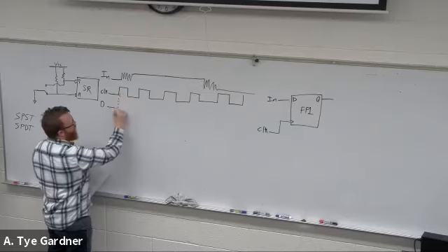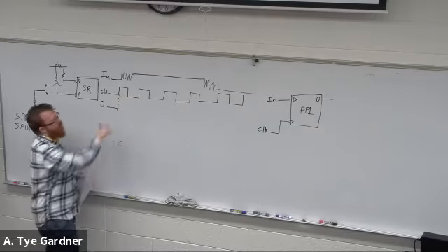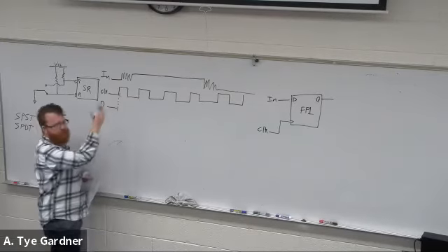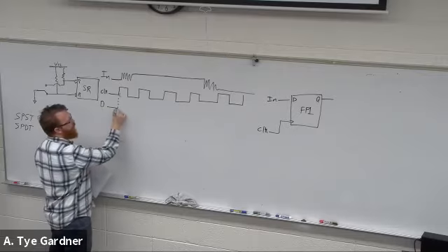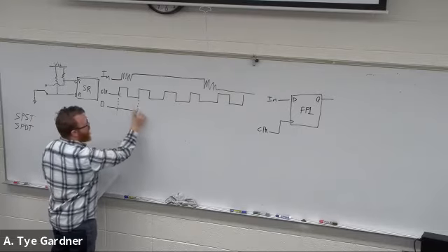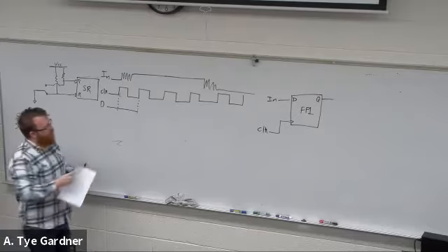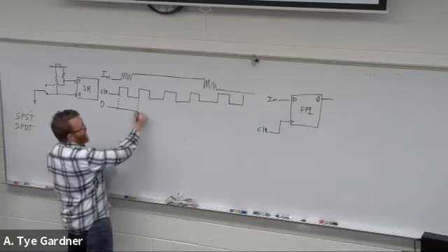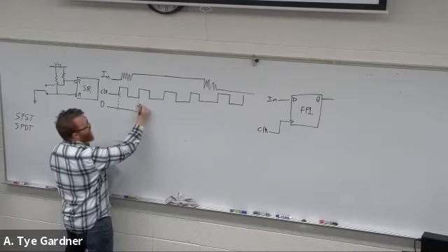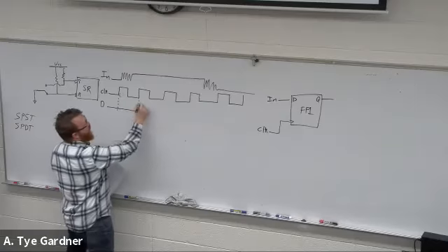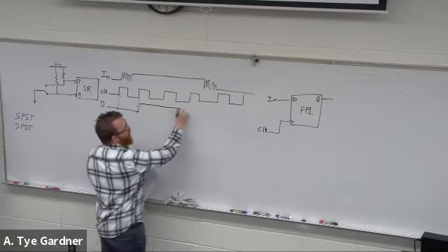Well, the first time it updates is going to be this rising edge. It's still going to be 0. I haven't thrown my switch yet, it's still 0. Nothing happens until the next rising edge, right? We're familiar with timing diagrams, we remember this stuff. Here, let's assume a small delay, just for the convenience of drawing it. And it's going to update to 1, and it's still 1, right?